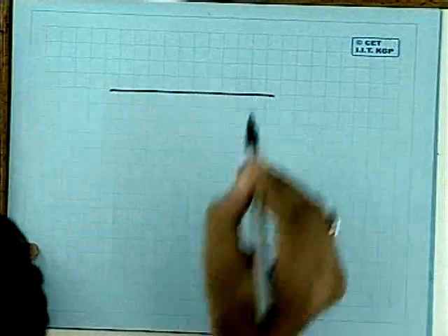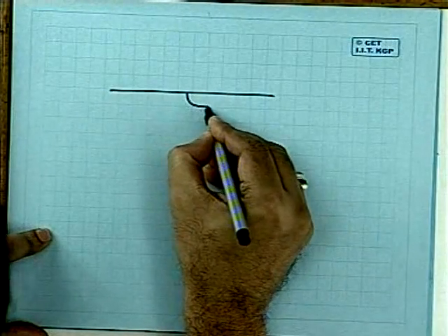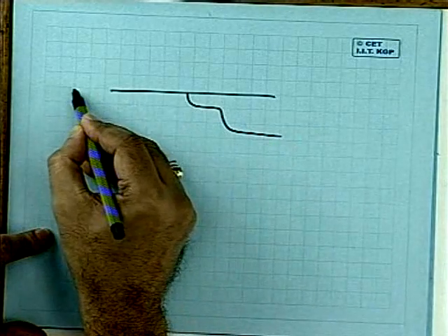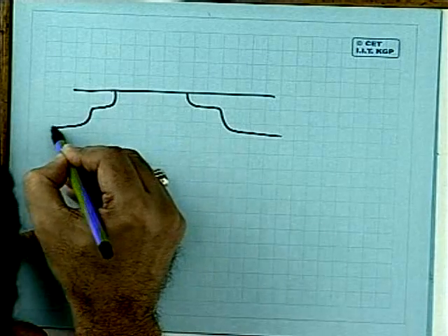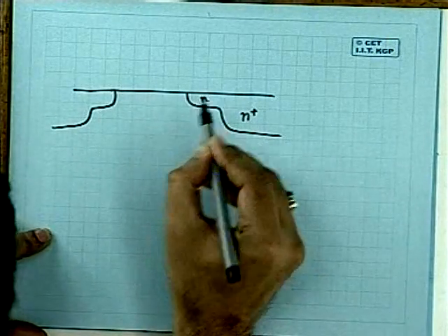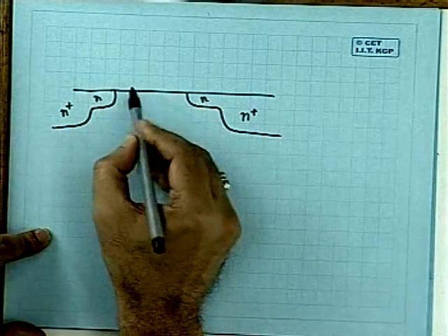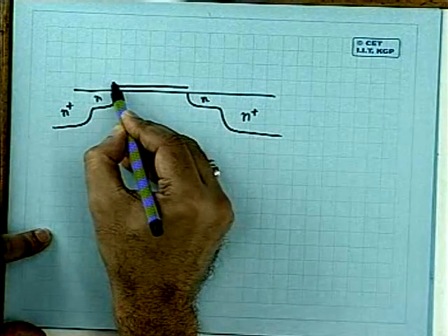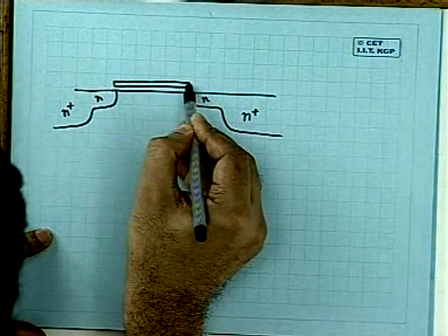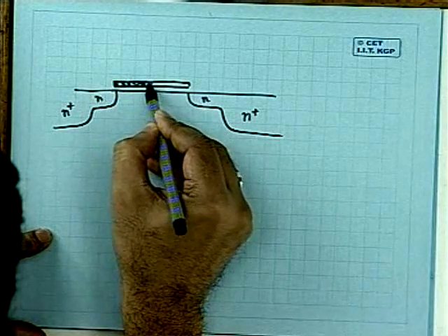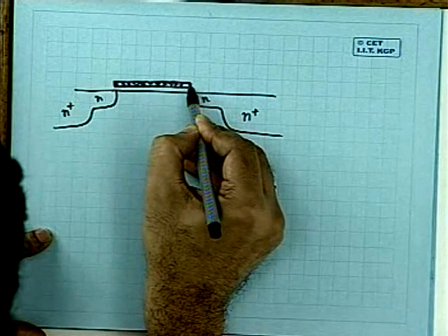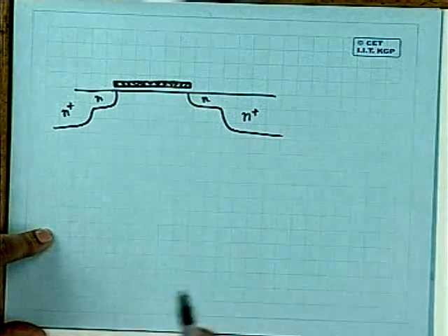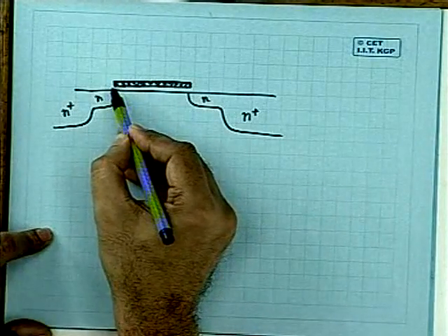So if you now see properly, what I have done actually, you have made a device like this in the drain side as well as in the source side also it is like this. Whereas this is N plus, this is N, this is N plus, this is N, and this is your oxide, and somewhere here you have your gate. And modern technology is such that the overlap is very small. There is a need for a little positive overlap, but that can be controlled precisely to almost 0 plus. Mathematically almost 0 plus. It is possible to make it very, very small.